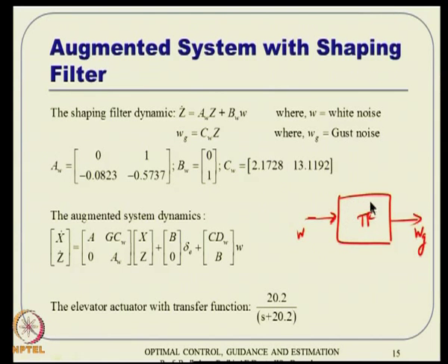So, if you realize this transfer function through a state space realization, it turns out to be like that. And because it is a filtering or estimation problem, this observable canonical form is the one recommended here. Remember, there are various forms of realizing a transfer function, and that is not unique. If you know a state equation, the transfer function is unique, whereas if you know a transfer function, realizing that in state space is not unique. Various ways exist, and because it is an estimation problem, the recommendation is you realize that in an observable canonical form. So, you do that, and then this AW and VW will come into the picture.